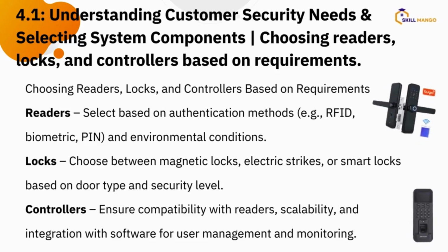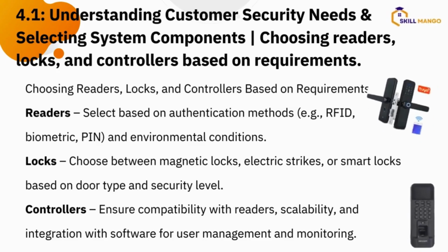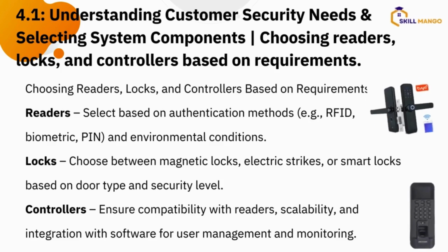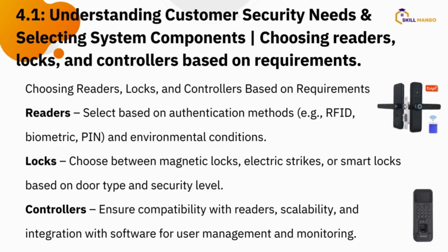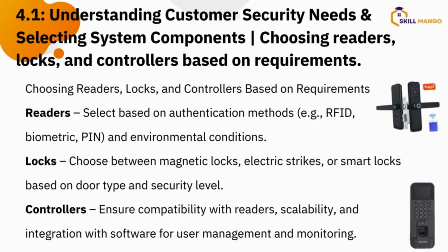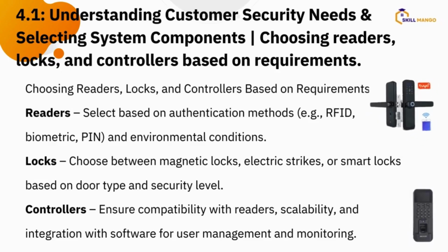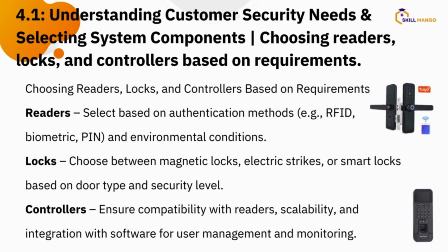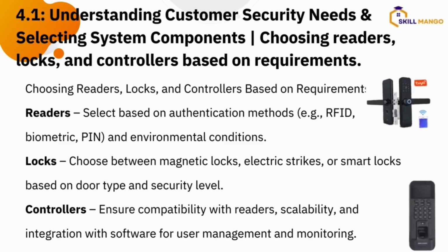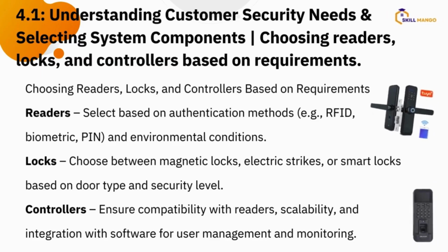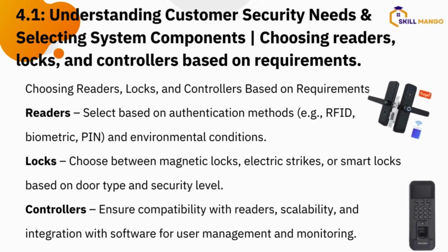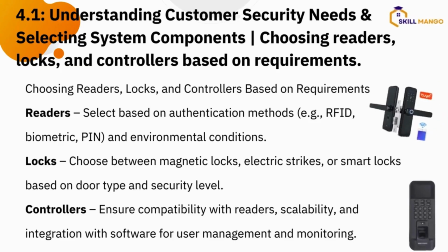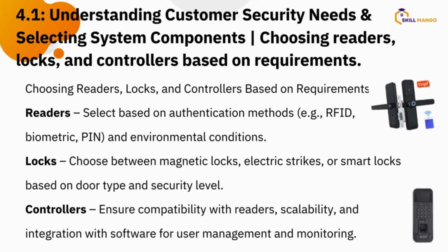All right. So you can use that to ensure that your door is well locked. And now it has advantages, it has disadvantages. This magnetic lock now, when there is power, is locked. When the power is out, let's say there's a power outage in the building, it is disengaged. You can now open the door and the door can be opened anyhow. When the power comes back, it sees power again, it contracts and nobody can open it again until you use a reader to open it. All right, that is a magnetic lock.